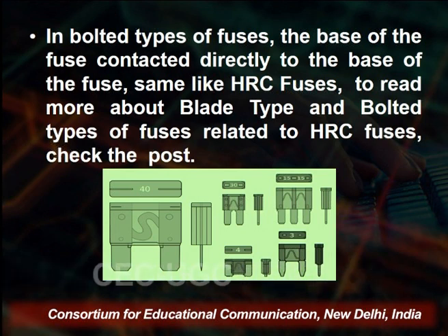The next type of fuses are the SMD fuses. What is SMD? It is the surface mount fuse, or the chip, radial or lead fuses. SMD stands for surface mount device, and the name comes from SMT, surface mount technology. They are chip type fuses, also known as electronic fuses, and are used in DC power applications like hard drives, DVD players, cameras, cell phones, etc. Space plays an important role because SMD fuses are very tiny in size and hard to replace as well.